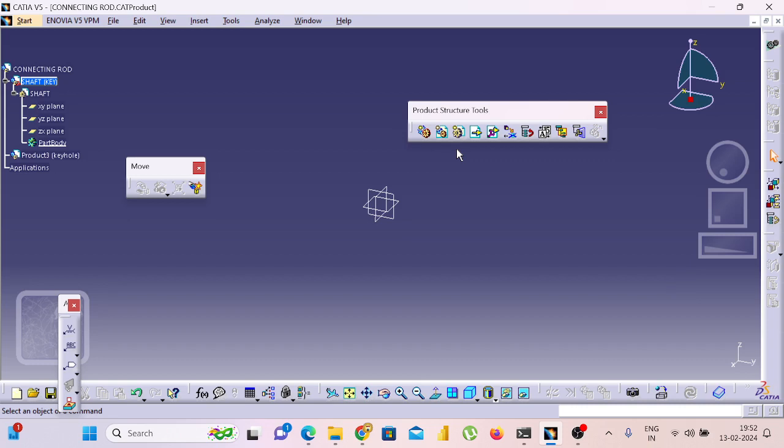These are the first important things. I will again recap what I did today. I drew one part in assembly and saved the part, and again I need to draw another part and save the part. While saving, the part will be saved in CATIA mode only. If you save in assembly mode or IGS mode, we cannot do the edit option, or we cannot add it into assembly, or we cannot do any other operations. For particular operations, the saving is entirely different. Whatever further operation we need to do, we need to save in that particular mode only.